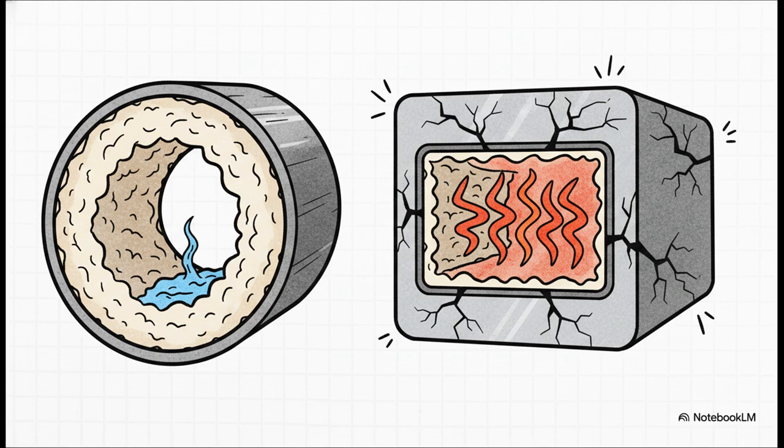In huge industries that rely on water boilers for steam generation, those calcium and magnesium salts precipitate out due to the extreme heat, forming these hard, rock-like limescale deposits right on the inside of the boilers. This scale acts as a stubborn insulator, which means industries can waste up to 25% of their energy just trying to heat the water through that thick scale. Plus, it clogs up pipes, leading to early structural breakdowns.